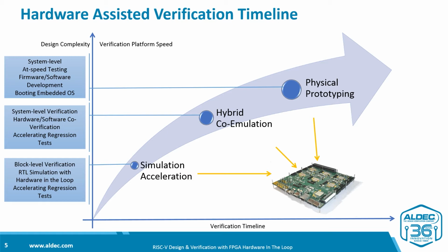Physical prototyping is the last pre-silicon verification stage. Again, the same FPGA board can be used to implement and run the entire SoC hooked with external peripherals and devices. Prototype implementation is optimized for speed, and so it's capable of running a complete software stack, including operating system, device drivers, as well as the top-level user or device main application.